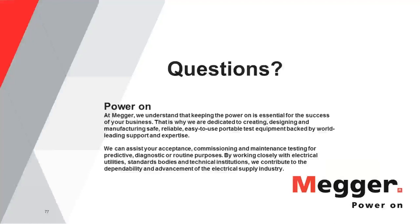So if you're working on old equipment that's been around for quite a while, maybe you can stick with a PI. But if you're on newer insulating materials and real high-end stuff, go to the DAR test.